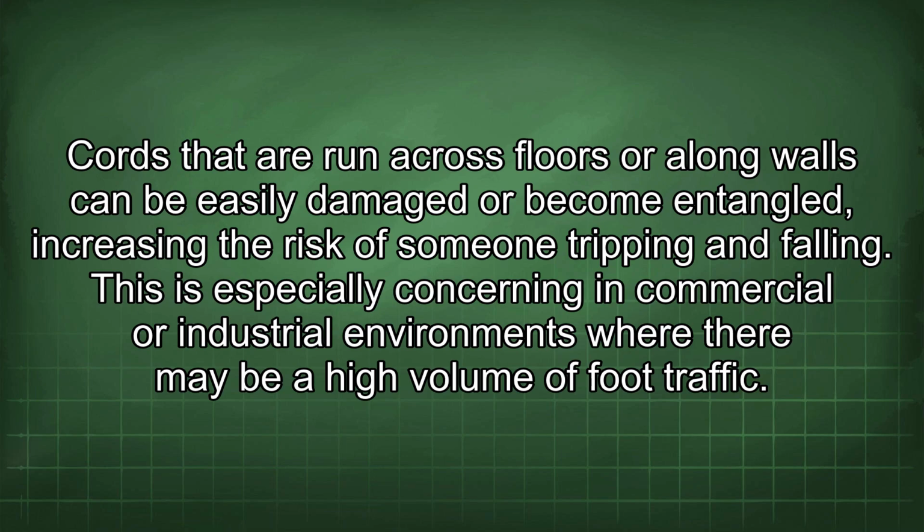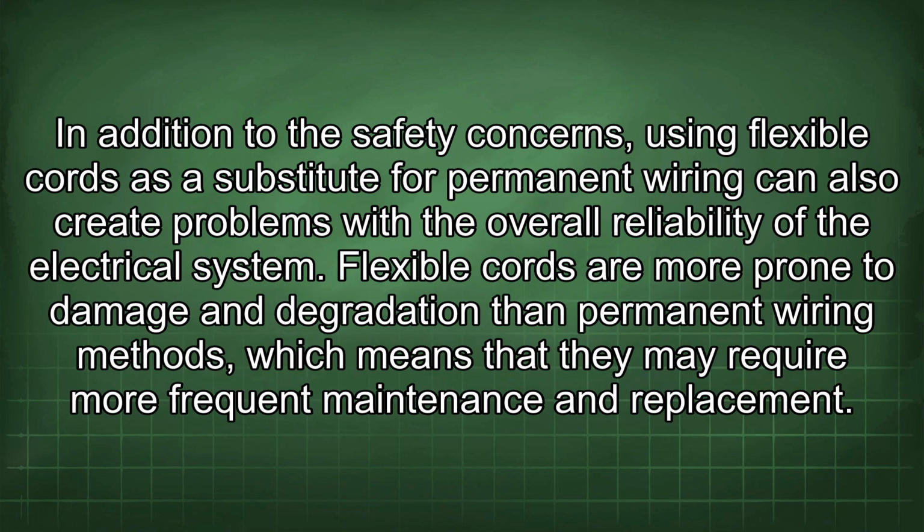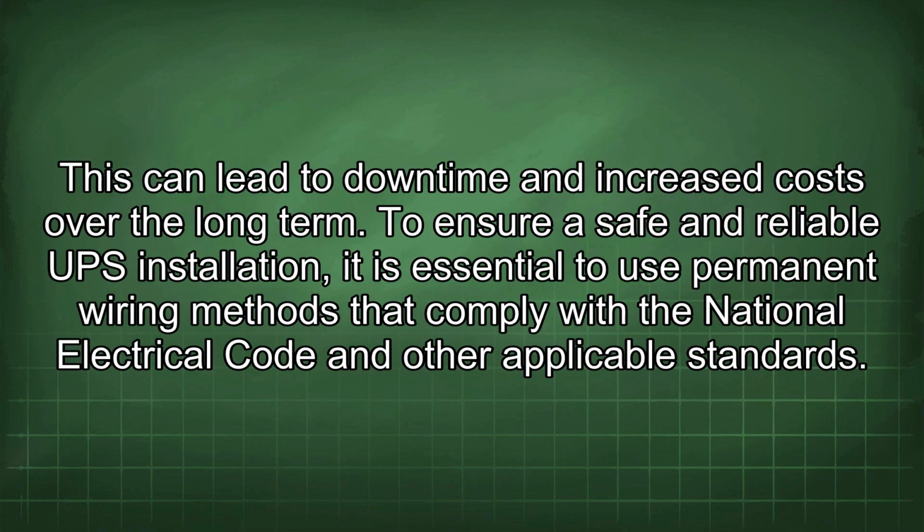Cords that are run across floors or along walls can be easily damaged or become entangled, increasing the risk of someone tripping and falling. This is especially concerning in commercial or industrial environments where there may be a high volume of foot traffic. In addition to the safety concerns, using flexible cords as a substitute for permanent wiring can also create problems with the overall reliability of the electrical system. Flexible cords are more prone to damage and degradation than permanent wiring methods, which means that they may require more frequent maintenance and replacement. This can lead to downtime and increased costs over the long term.